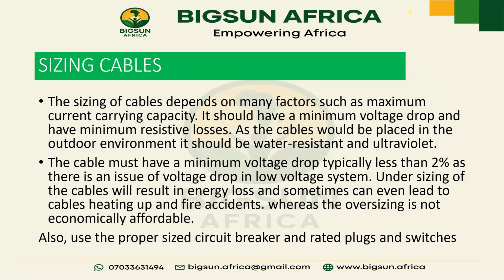So, cable sizing. Cable sizing depends on many factors, such as maximum current carrying capacity. What this means is how much current a particular cable can carry. Okay, we should have a minimum voltage drop and a minimum resistive loss. As the cables will be placed in the outdoor environment, they should be water resistant and ultraviolet resistant.